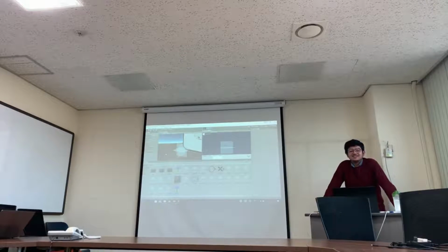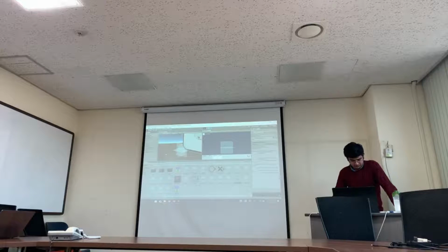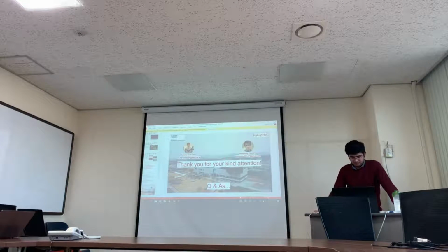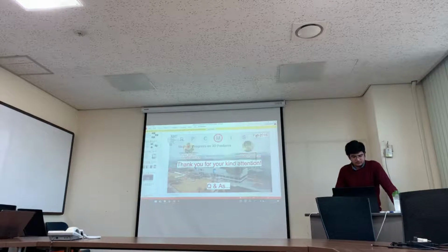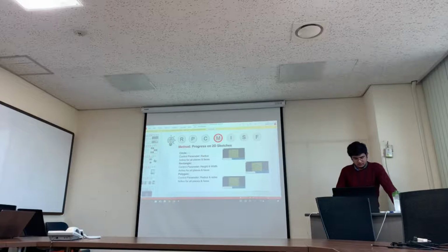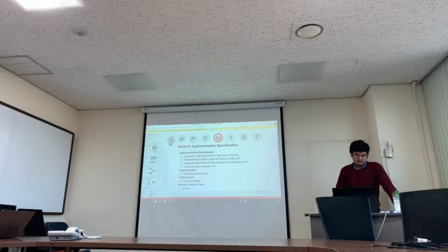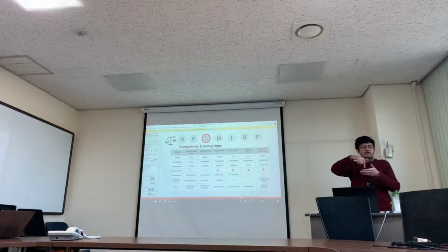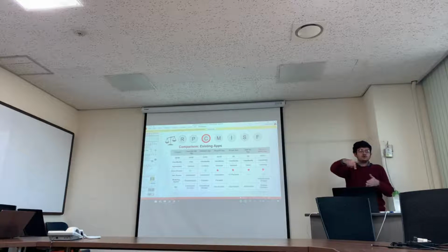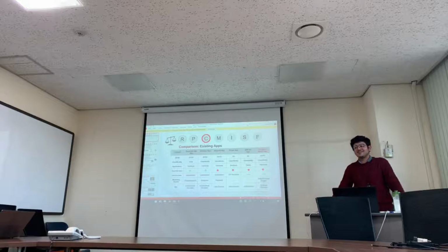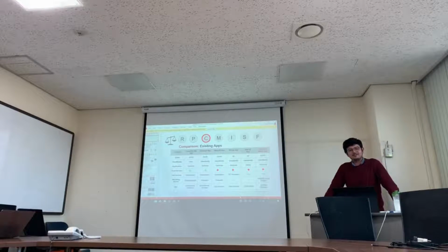Another question. You use the mesh in the circle, the 32 sides. Is there any reason why you chose 32? We can increase it. There is no specific reason. It's just the minimum number of sides for which it looks like a circle. Because the triangles are on the surfaces, it looked nice with 32, so we ended with it. So your choice is because of the shape and the calculation. Yeah.